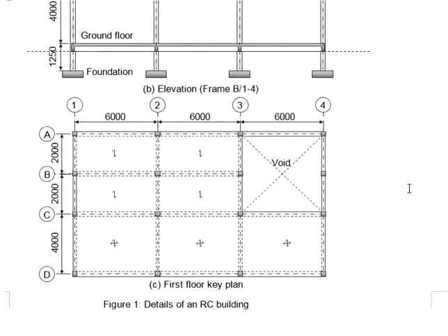Next is about the principles of load distributions. We know that these slabs are one-way slab. It is because the Ly per Lx ratio is more than 2.0. Because of that, we will know the load distributions. It will be half of the slab will go here, another half will go the other side.